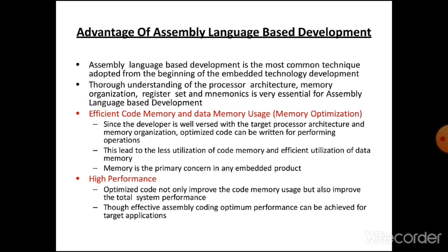Then, what are the advantages of assembly language based development? The first one is efficient code memory and data memory usage. Since the developer is well versed with the target processor architecture and memory organization, optimized code can be written for performing operations. This leads to less utilization of code memory, which is the primary concern in any embedded product.